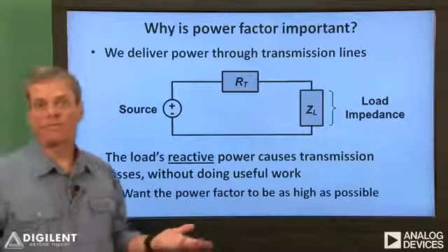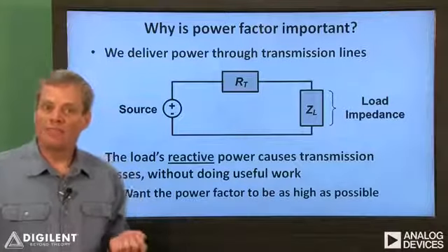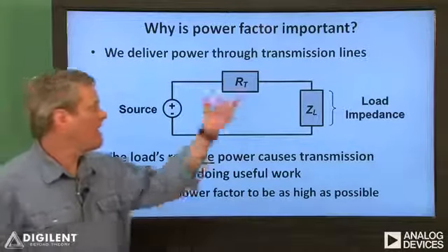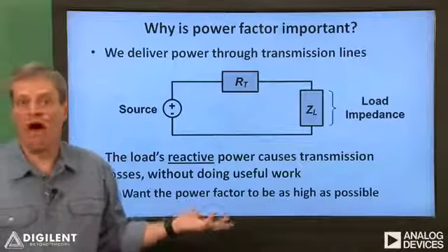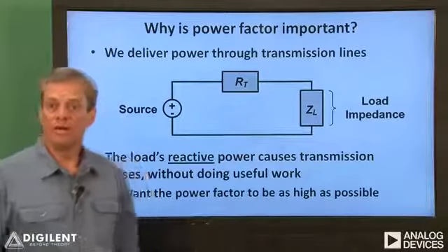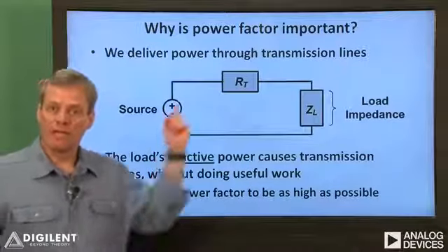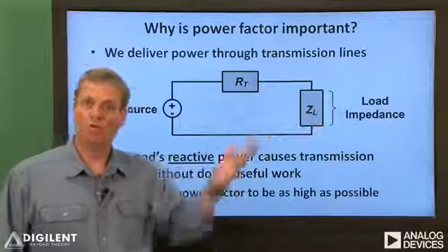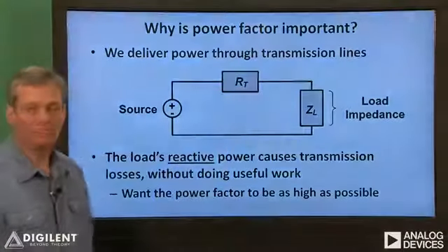It typically doesn't serve any useful purpose. However, trading the reactive power back and forth does cause power dissipation in the transmission process. This power is just lost. We don't get anything for it. Keeping the power factor of the load high reduces the reactive power traded back and forth between the source and the load, which reduces the losses associated with trading this power.